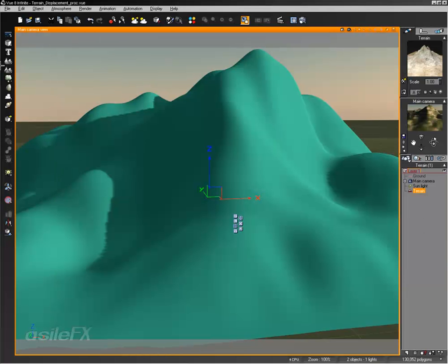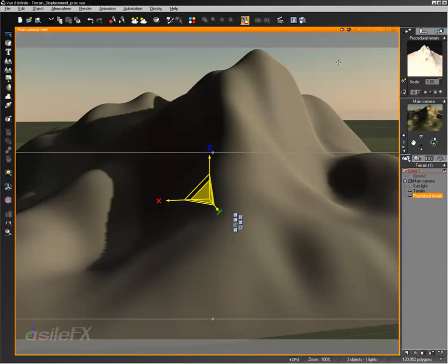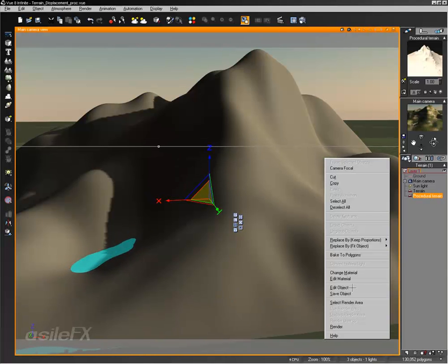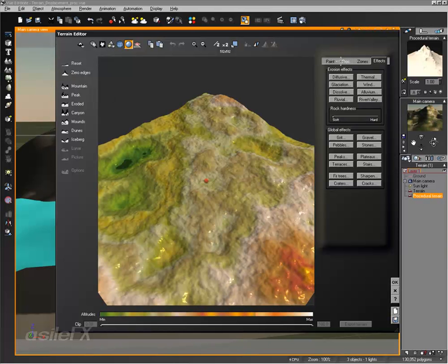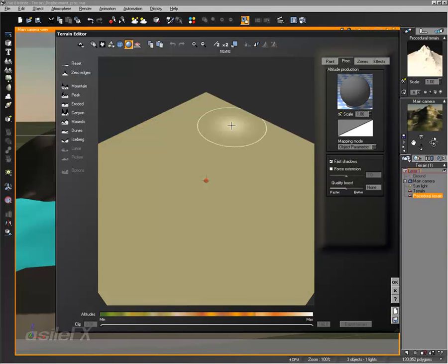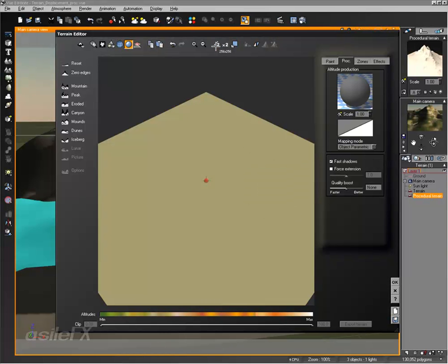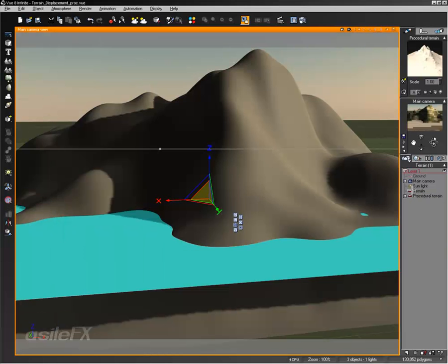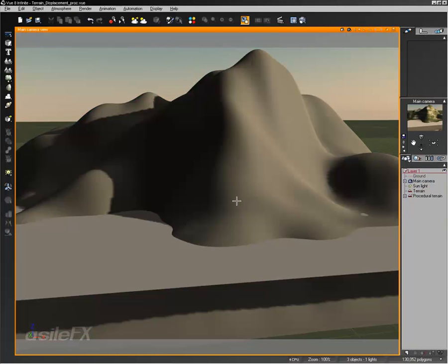But I'm not going to rely on that, so I'm going to create procedural terrain, go ahead and scale it up to match the approximate size, edit the object, go ahead and reset, turn off zero edges, go to the procedural, reset the function, and then we can paste in. And I do need to scale this down to the same size as the other terrain, 256. Looks like maybe it's not working. Go ahead and try that again, performing another copy and paste.